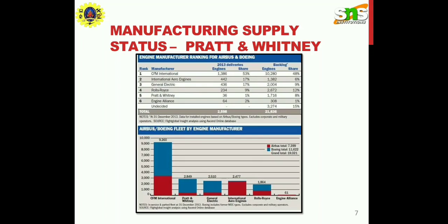Turbo machines can finally be classified on the pressure changes across the blade. Impulse turbo machines operate by accelerating and changing the flow direction of fluid through a stationary nozzle, and the nozzle changes the incoming pressure into velocity. The enthalpy of the fluid decreases as the velocity increases, and the pressure and enthalpy drop over the rotor blade is minimal.